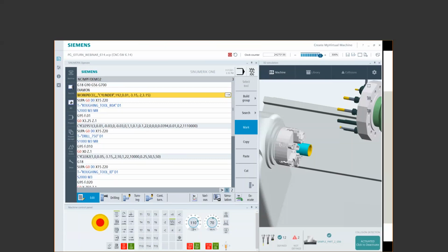If your machine is fundamentally a milling machine, like a 5-axis mill that has a torque motor and can do turning capabilities, in the DMG portfolio, they call it an FD machine. That is what we call a mill turn. And in that case, the default strategy would be diameter mode off, because by default, that's a milling machine. And milling machines, you generally would not have diameter mode on until you went to a turning scenario. So just keep that in mind.